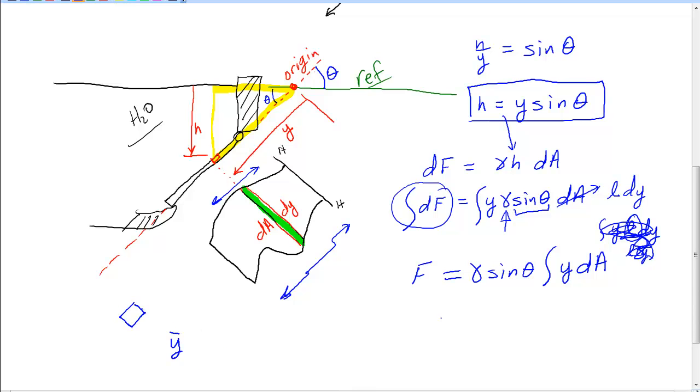If you had several strips here, what you're generally doing to find the y bar of a composite area, I'm just making up some stuff here, is you sum the y bars times the area, and you divide by the total area, and I need to put these as indexes. So here's 1, 2, 3, and 4.